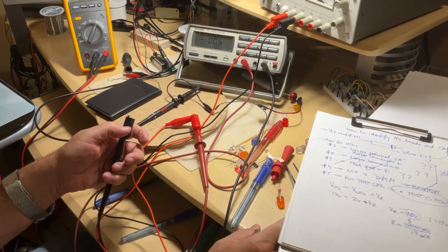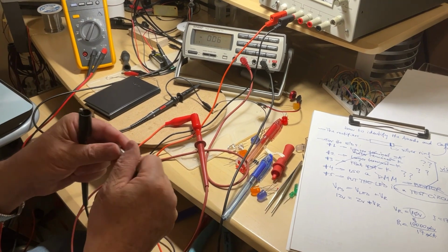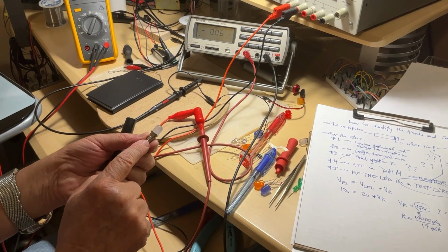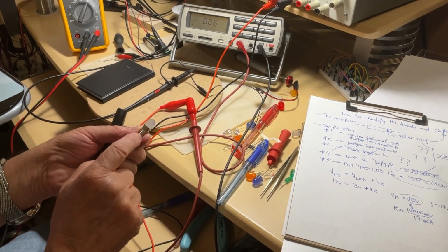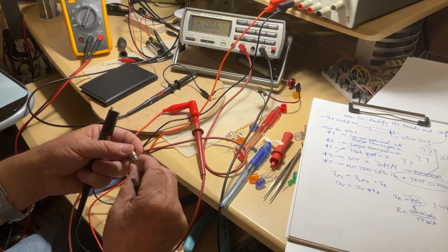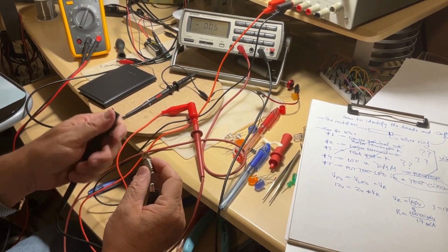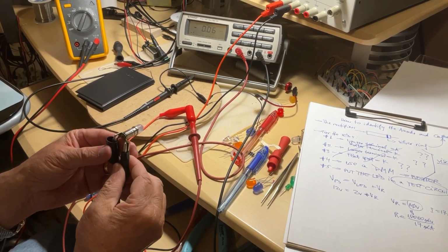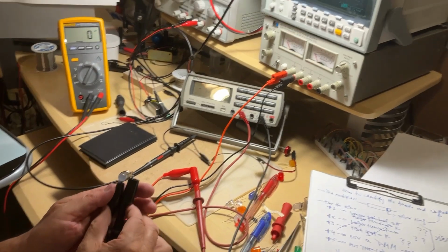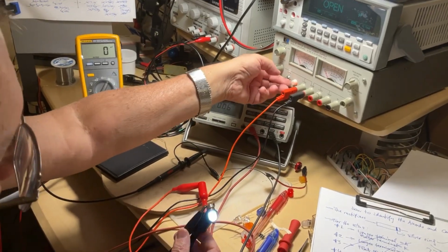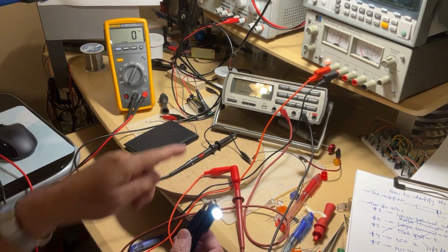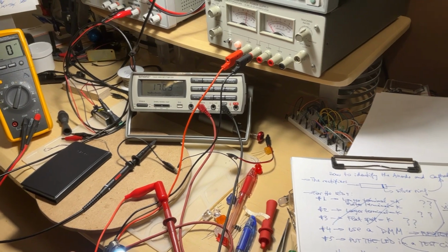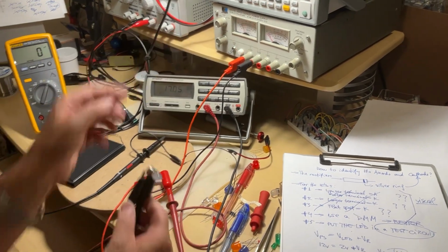And now I'm picking up another one intended for the same purpose, to replace a 12-volt incandescent light bulb. But this one comes on an Edison socket. It's not bayonet, it's Edison socket. Also 12 volt. So I do the same. I connect one leg and the other one. And when I put the power on, oh, this is a white diode. Take a look, what is the amperage? It's exactly the same, 17 milliamps. So, remember, 17 milliamps.